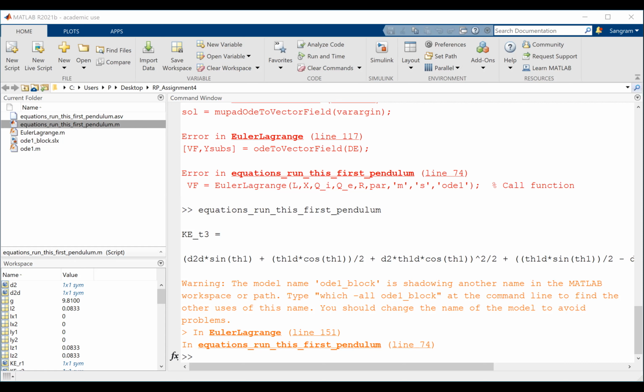If you look at the robot arm, in that robot arm, you would have a rotary motor which would rotate the revolute joint, and then you have a linear transducer that would extend or contract the prismatic joint. So you would have a rotary actuator and you have a linear actuator.